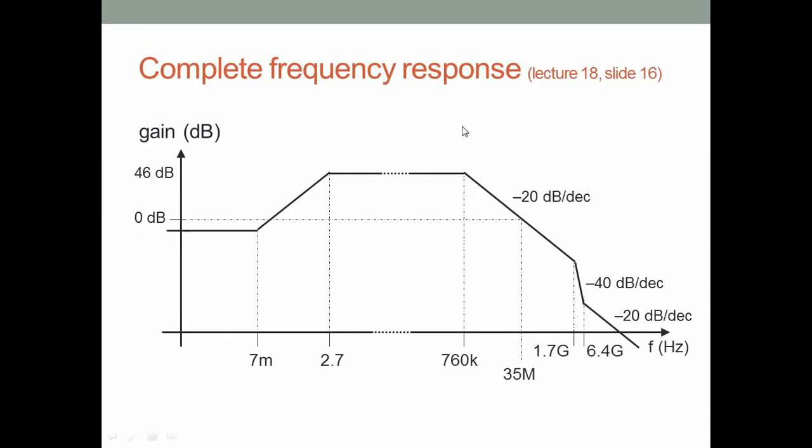All right, so if I have many poles on this side, the open circuit time constant method applied to the high frequency transfer function or the high frequency equivalent circuit gives me p1. If I were to apply a short circuit method to find the frequency, that will give me p2.